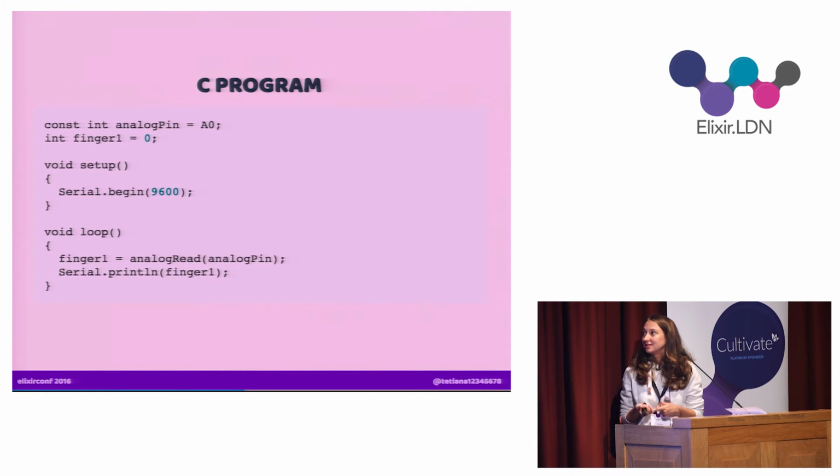Okay, and to tell Arduino that it's supposed to be reading the data coming from the sensor, you write a little program which says that I'm using the analog pin, A0 in my case, but it could be any. And then you just read the value coming in. In this case, with the serial print, it's just going to print whatever value comes in.